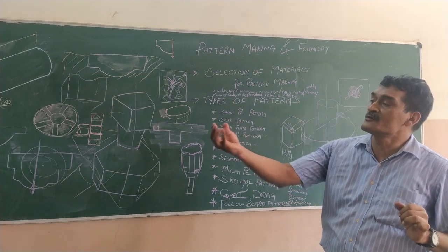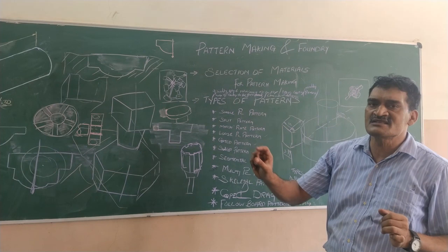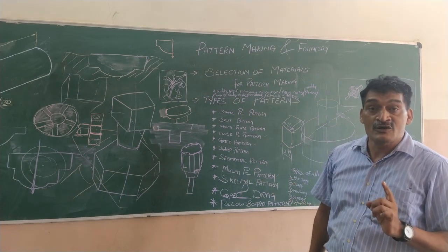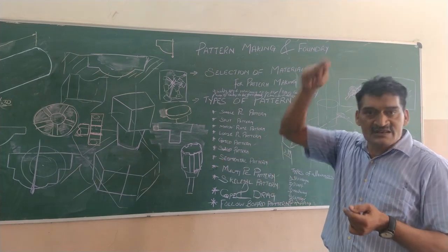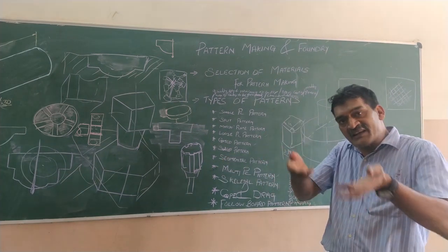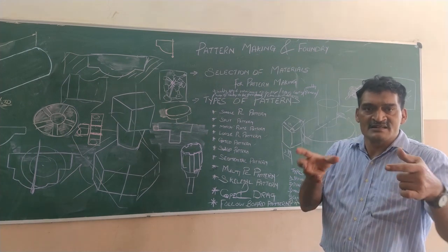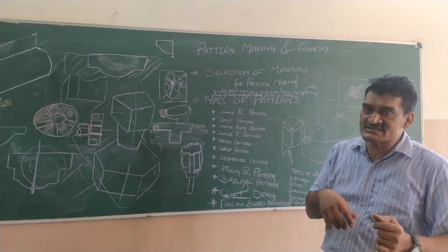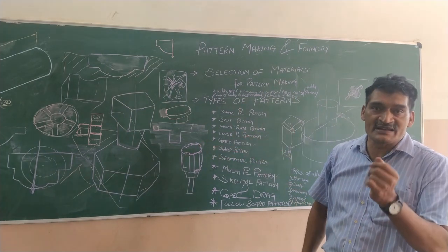Okay, and there's one more pattern, 1 inch by 1 inch, and the length is 2 inches. Now, on which of the patterns do you think you will hit harder for the pattern to be removed? It is of course on the bigger one, that is 6 inches by 6 inches, and less force will be applied on the smaller pattern.